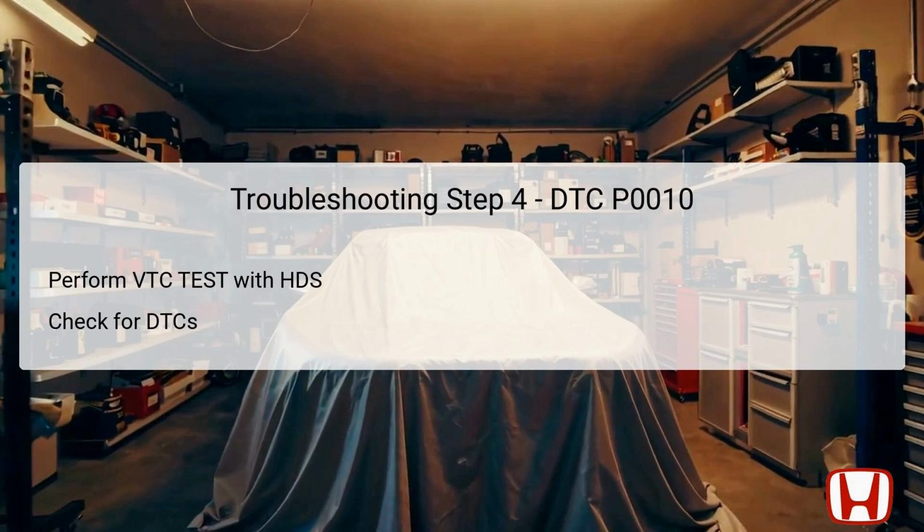Any new or recurring DTCs will provide immediate insight into whether the troubleshooting process should proceed or if the system is functioning properly at that moment, enabling efficient and accurate diagnostic procedures. The fifth troubleshooting step is determining whether DTC P0010 is indicated after conducting the VTC test.